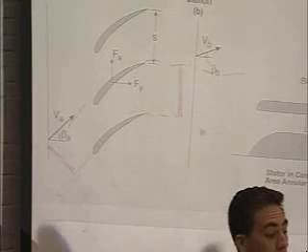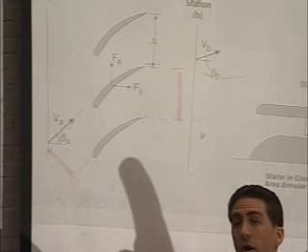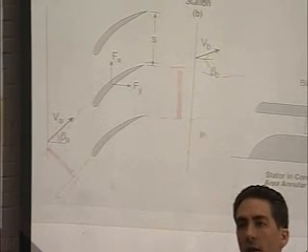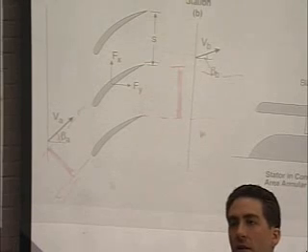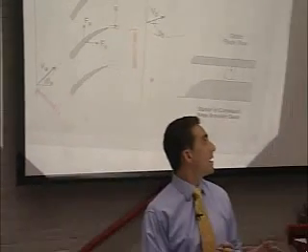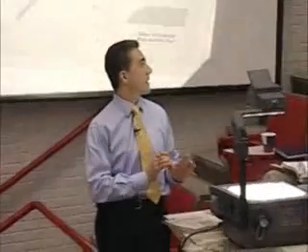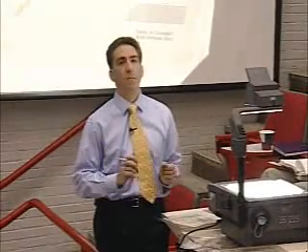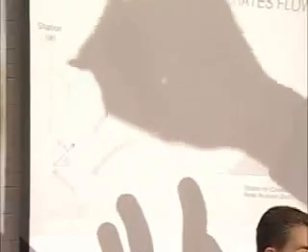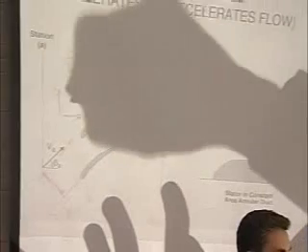So there are forces on these blades. There are torques, but they're not moving, so they don't do any work. They just take one kind of energy and turn it into another. Is that okay? Conceptually, you have to really be able to unwrap the compressor. So flow in this direction is tangential. Flow in this direction is axial.